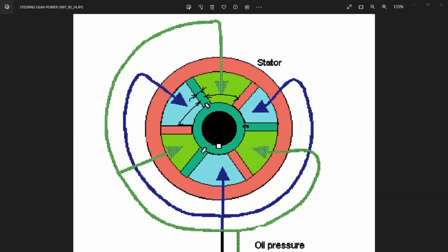So basically, if you've got 3 of these angles, like 3 rotors and 3 stators, you can only give 70-degree movement of the rudder fully to one side. But if you have only 2, then more angle of movement is possible, because the minimum thickness of the stator is obviously going to be the same. So you can get more angle movement.